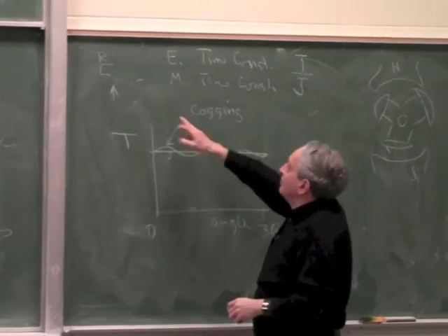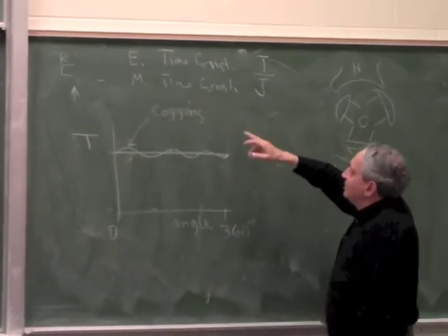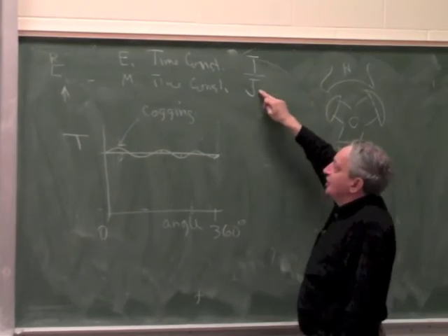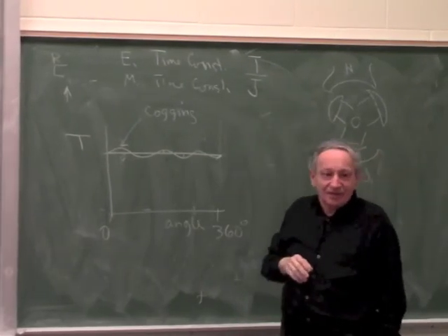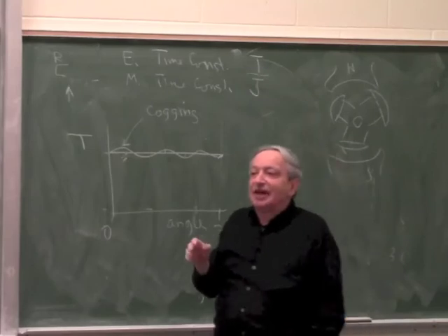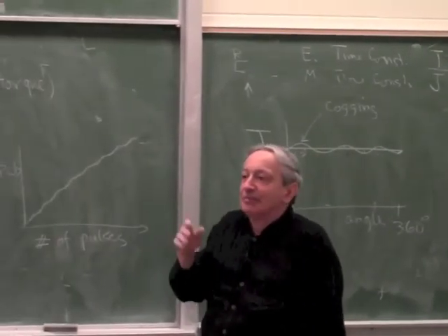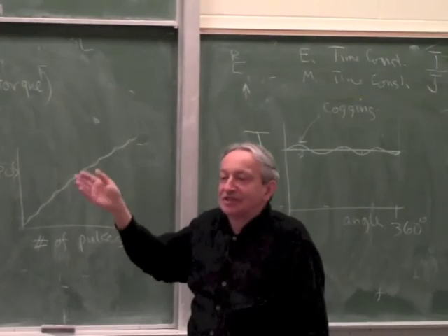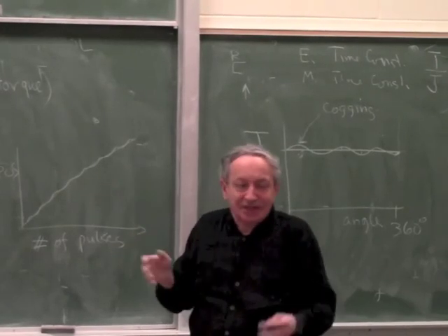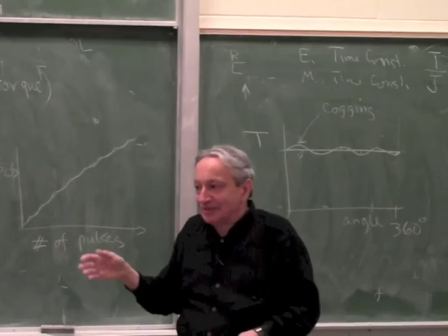And mechanical time constant is basically dependent on torque to inertia. Mechanical time constant means in how many milliseconds it will reach 1 minus 1 over e, like 63% of speed. Just like a time constant is defined in a capacitor, right?